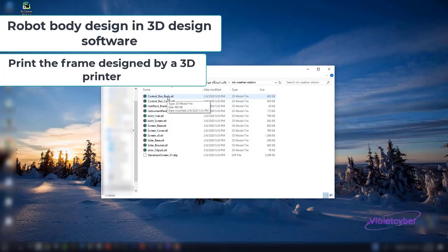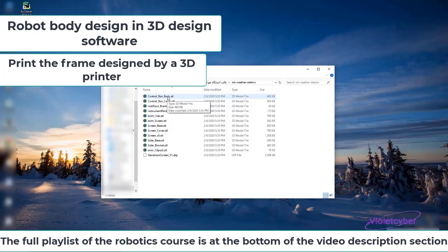You can even see a preview of your template, resize it, and perform many different operations on it before printing, such as choosing the print quality. Quality determines whether the part is very strong and compact or lower quality and flimsier, and you can control all of this using the printer's software before printing.